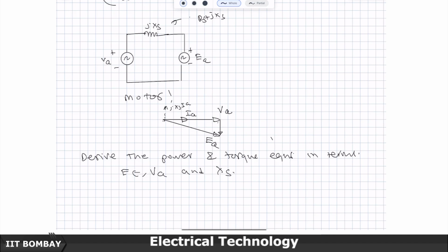So, those armature currents are creating another rotating MMF field, and that rotating MMF field is interacting with the MMF created by the rotor's sinusoidally distributed rotating travelling wave, and you get a net superposition of these two, which is the actual flux distribution in the air gap.